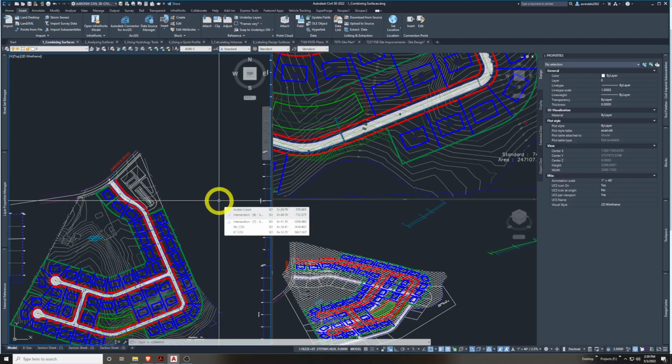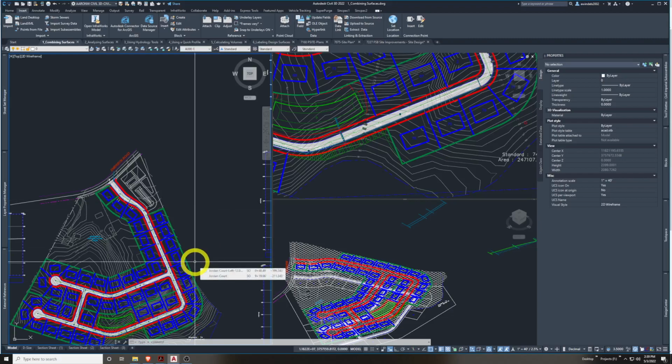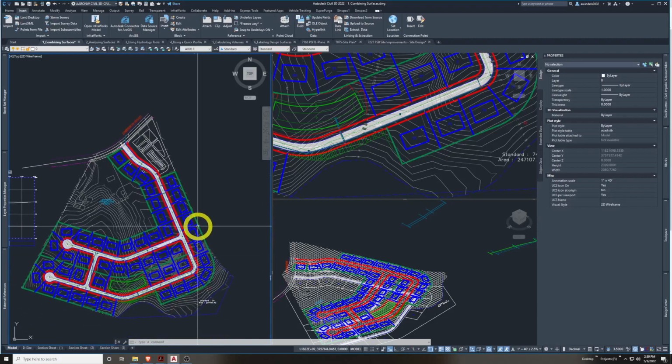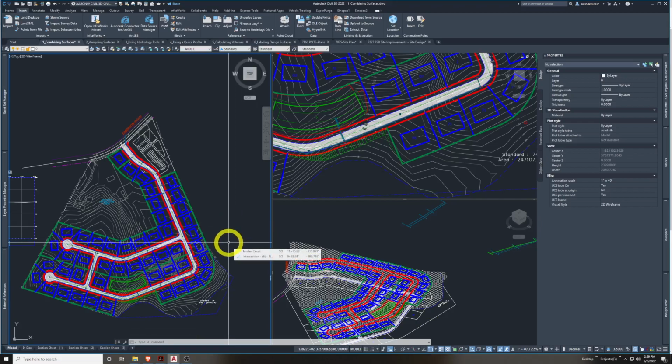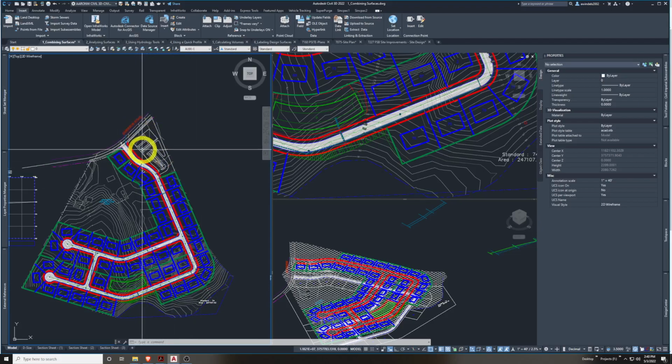In 18.1, we're basically going to create a final surface combining many surfaces of the lot gradings, the road elevations, ponds, and other smaller daylight areas. Let's start by going into the left viewport here. You notice right away the line weight thickness is on. You can turn that off if it bugs you. I'm going to leave it on for now so it really emphasizes the feature line thicknesses of the blue, the green, and the red. There's some small little surfaces and ponds and stuff. Looks like we have a little parking lot development starting to be designed up here in the kind of clubhouse